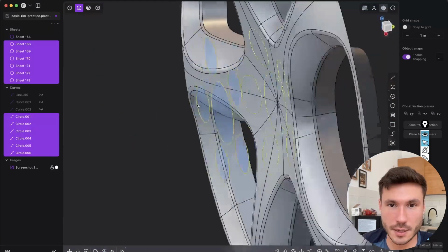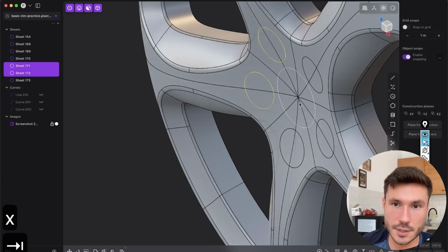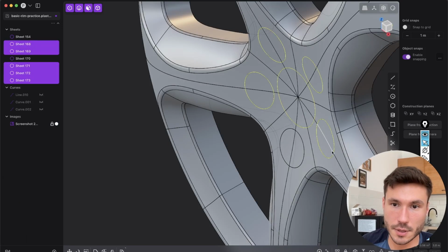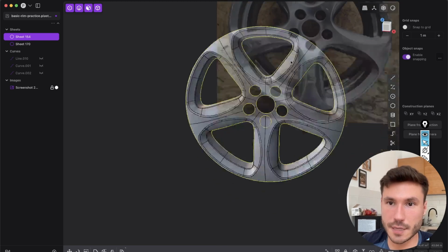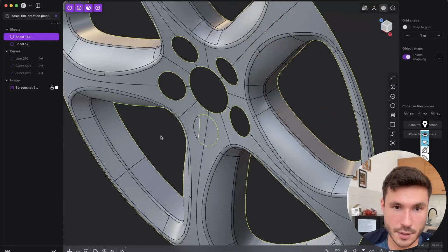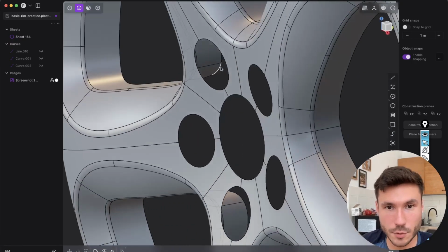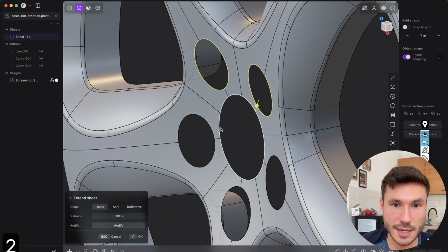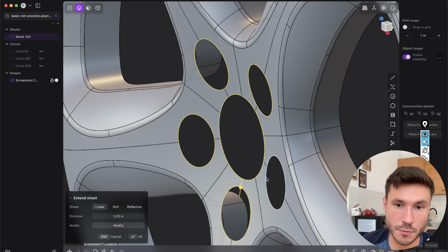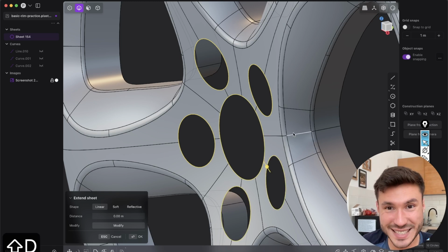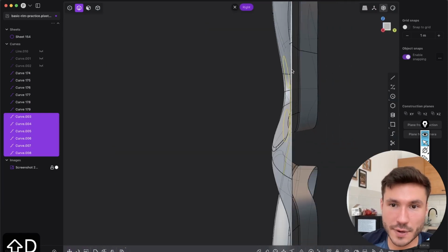surface. Fine. And just delete all of those curves and delete those extra surfaces, because obviously we have some holes, right? So delete this last one. And now we have to do something. First of all, select with Alt Shift click all of those boundary loops here, and Shift D to duplicate them again and go to the right view.